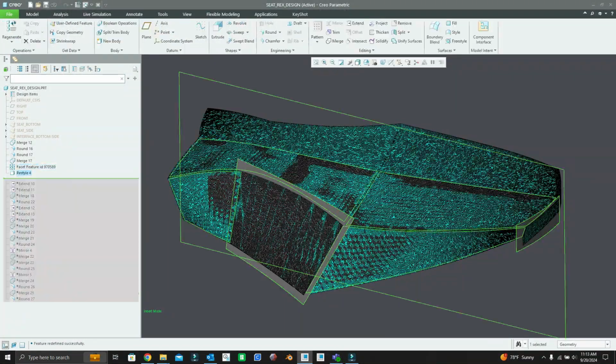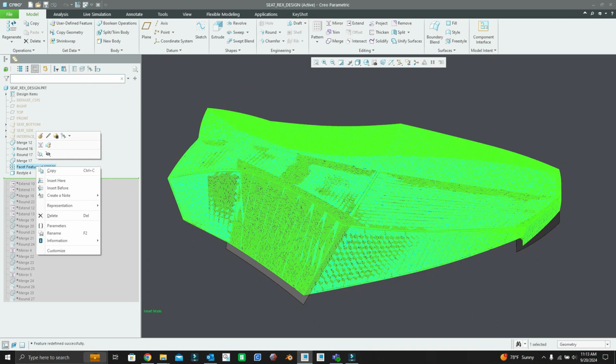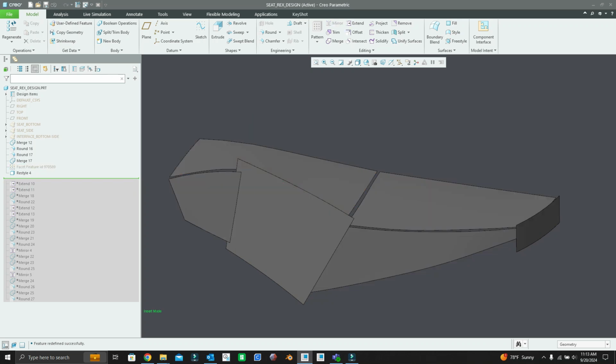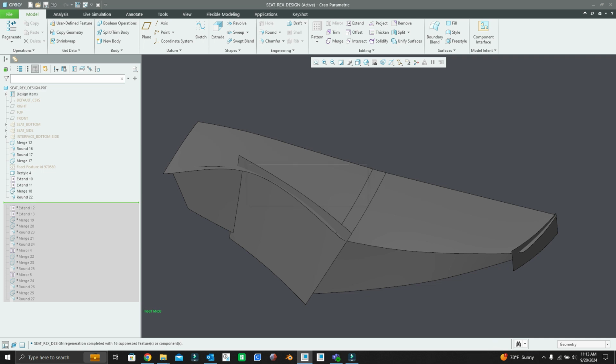So we'll exit out of here. And it's simply, if you guys remember going back to the extending and merging of the surfaces, this is what we're going to do here. So we're extending the surfaces out, making sure that they intersect each other. Then after that, we're going to continue to merge them together and add rounds in this case. Extend, extend. We can just go step by step here.